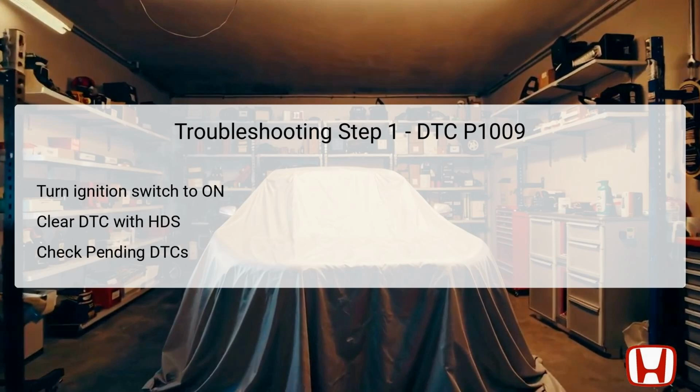Begin the troubleshooting process by turning the ignition switch to the on position, which powers up the vehicle's electronics without starting the engine. Next, utilize the HDS, Honda Diagnostics System, to clear any stored DTCs. This step is essential to reset the system and eliminate false readings.